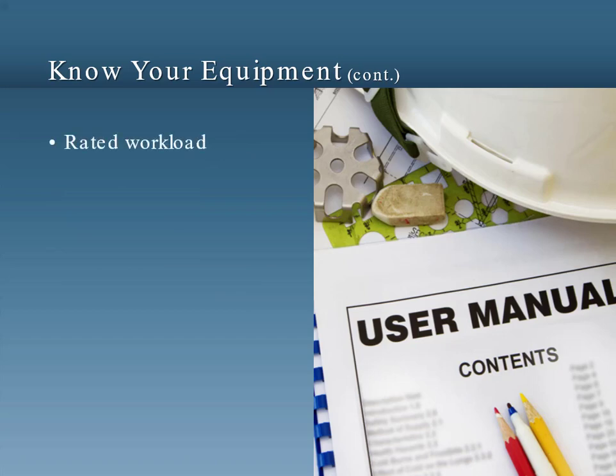You should also know the rated workload of the lift. This information will be posted right on the equipment itself. Knowing the rated workload will help prevent tip-overs. Some aerial lifts, for example, are only designed to hold the weight of 1 or 2 workers. They may not have the additional capacity to take on a load of materials, tools, and so on when they are fully extended. The maximum platform height will also be posted on the equipment.